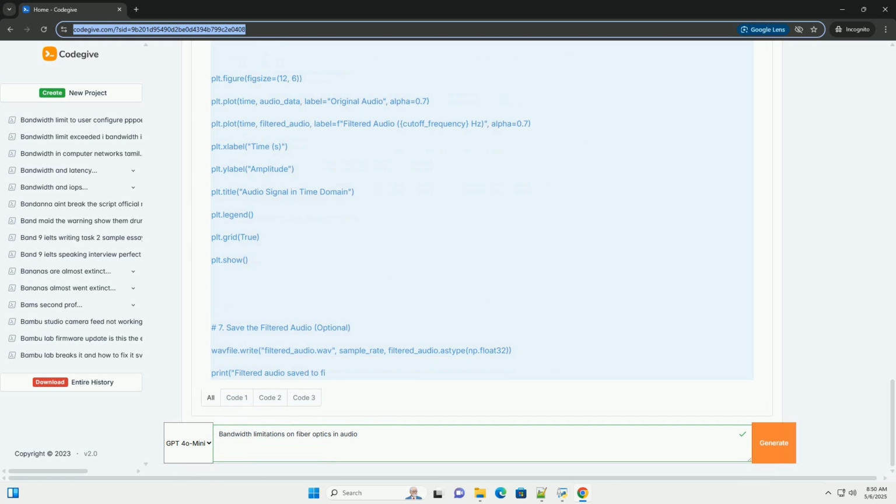Single-mode fiber, SMF, has a very small core diameter, allowing only a single mode of light to propagate. SMF offers significantly higher bandwidth and can transmit data over much longer distances. SMF is typically used for long-haul telecommunications and broadcast applications. The key difference affecting bandwidth is modal dispersion, see below.